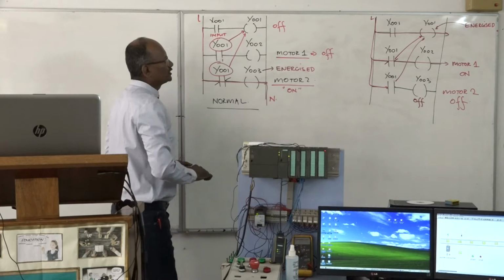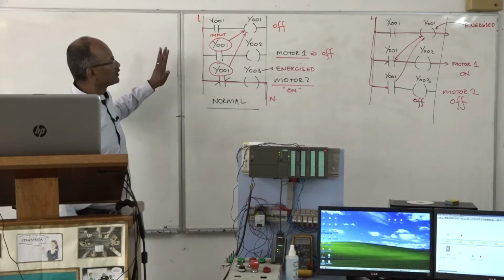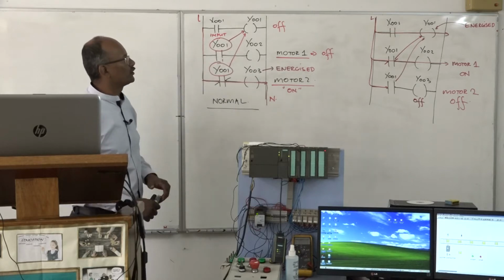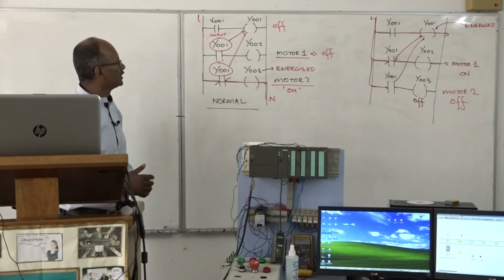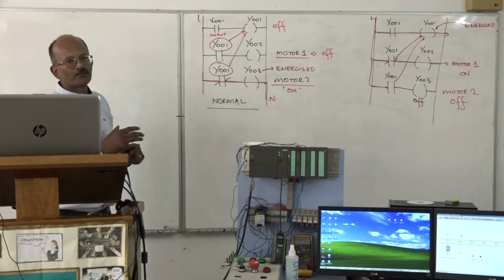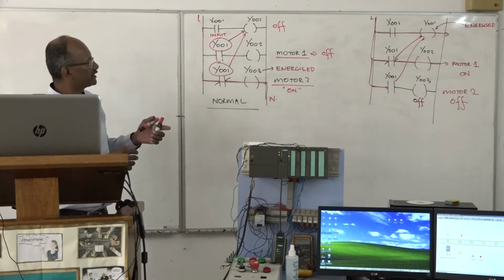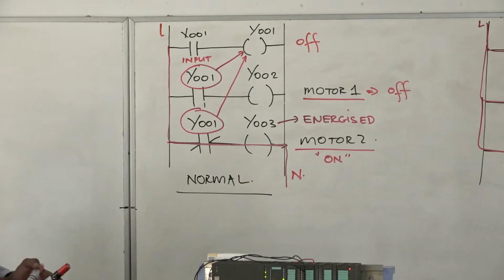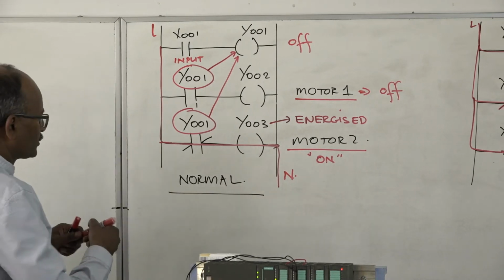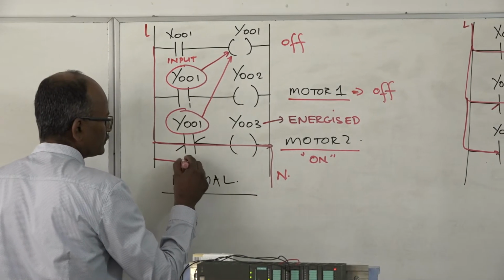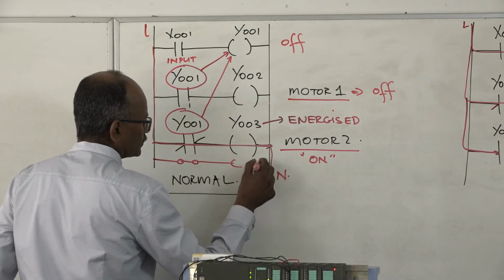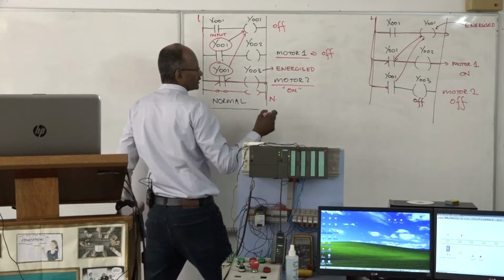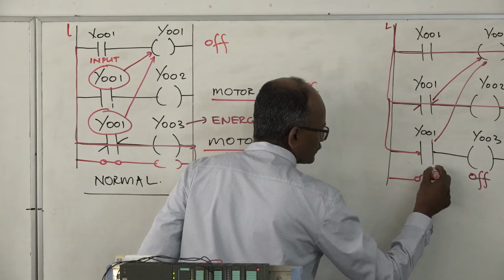So you need to understand the transition from a circuit being de-energized to a circuit being energized, or when I press the start and stop button. When you are doing this, feel free to represent your PLC circuit symbols by electrical circuit symbols. For example, I could initially have done this here when it's de-energized, and then when the circuit is energized, I would do that.